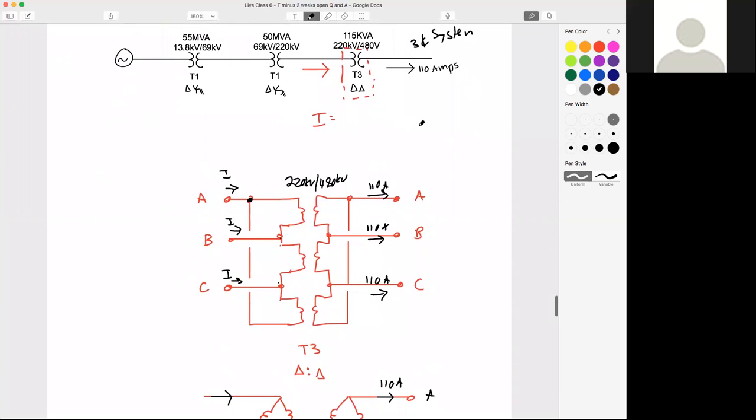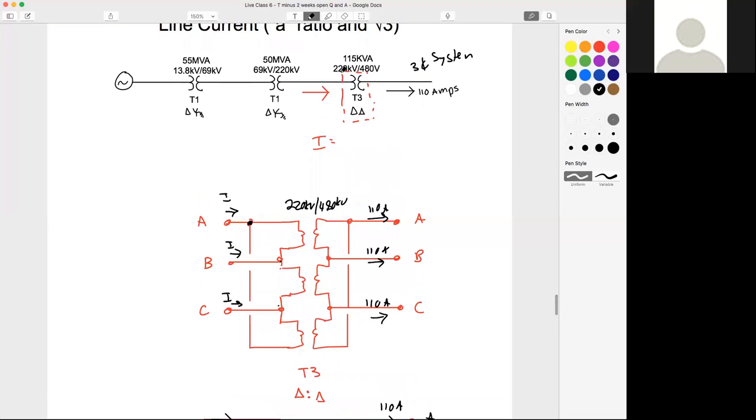So all we do is we know this is a step down transformer. And so if our voltage is going down on this side, then on this side, is our current going to be bigger or smaller? Our current is going to be less, right? If our voltage is bigger, S equals VI, and S1 equals S2. So if our voltage is higher on this side and lower on this side, then our current is going to be the opposite, right?